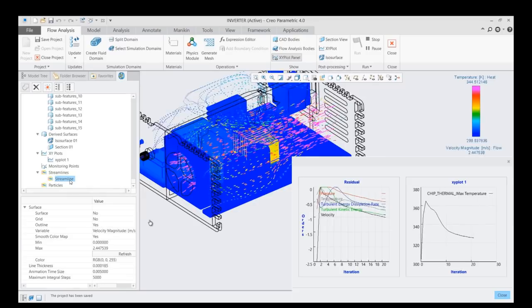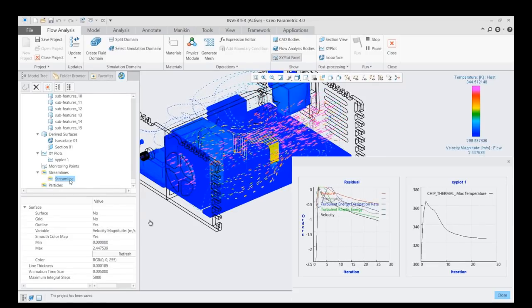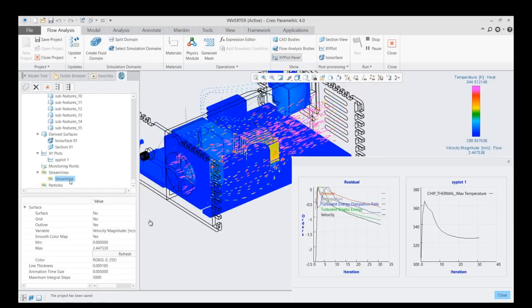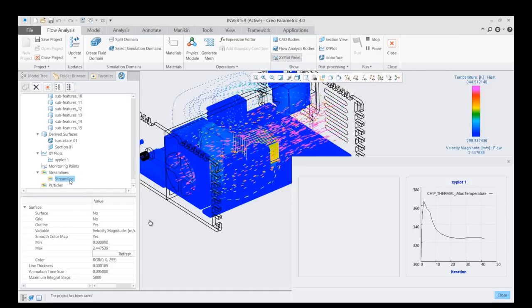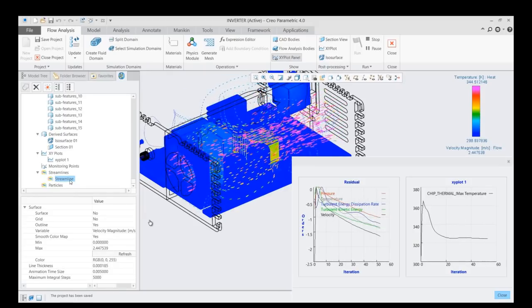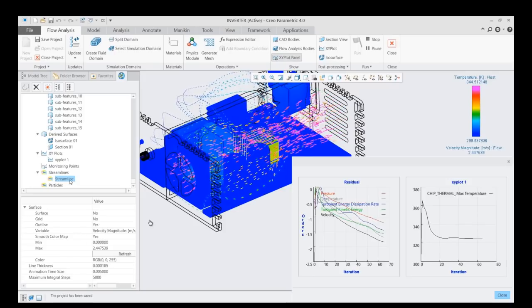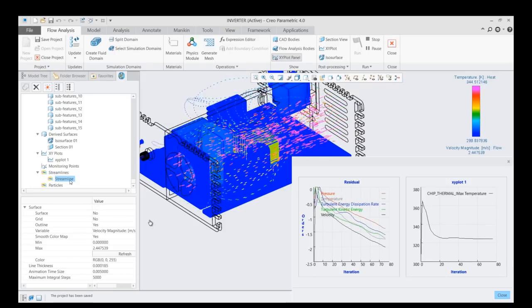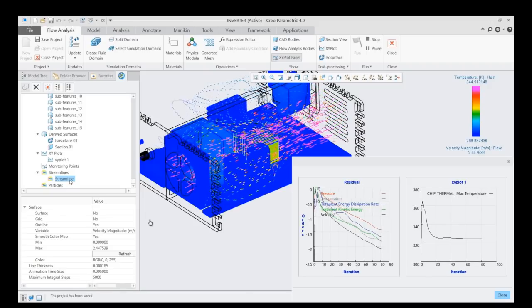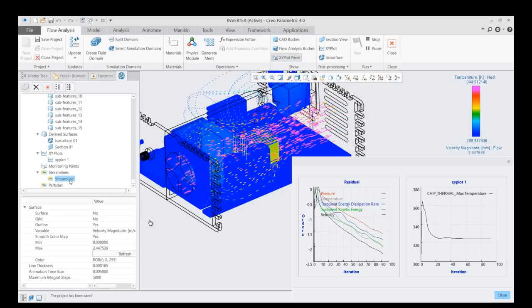The thing to note here is, as the experiment is running, you can see how the heatsink started off really quite bright orange, bordering on red, and then it's settled down to a yellow color now, almost bordering on green. The other thing to note is the XY plot. Again, we started at 300 degrees Kelvin, raced up to about 365, and we've now come down to a steady state of something approaching 325.